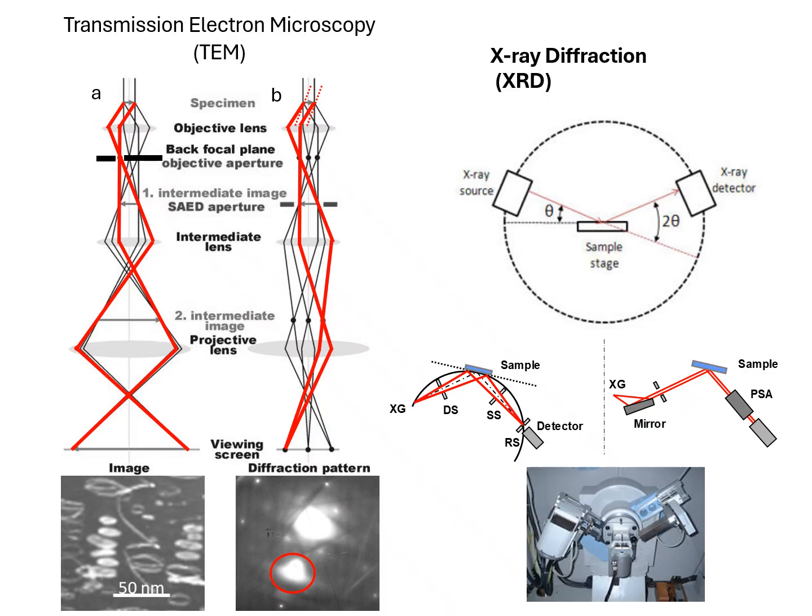electrons are scattered from the material, and collecting that at the back focal plane, or an image of the back focal plane, of the objective lens, giving what is called a diffraction pattern. Now, the diffraction pattern literally is the Fourier transform of whatever is in the sample. So in this particular case, it's really the Fourier transform of the planes.